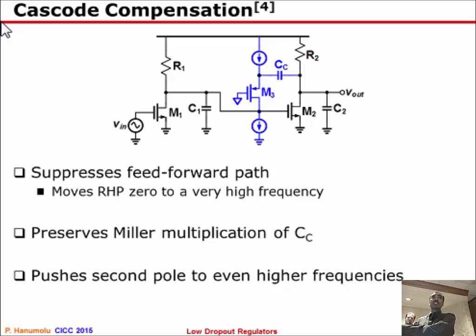If you make the output pole dominant and have a very large capacitor, then what we are really trying to do is not let the output voltage change by having a big enough capacitor. And in this context, if you have any ESR and all that, it's going to degrade. You're going to get overshoot and ringing, and the transient response is degraded. But that is one way. The other way is you try to make the loop bandwidth as fast as possible, and as a result, you can regulate the output to not go beyond the error tolerances, even in the presence of load current variations.